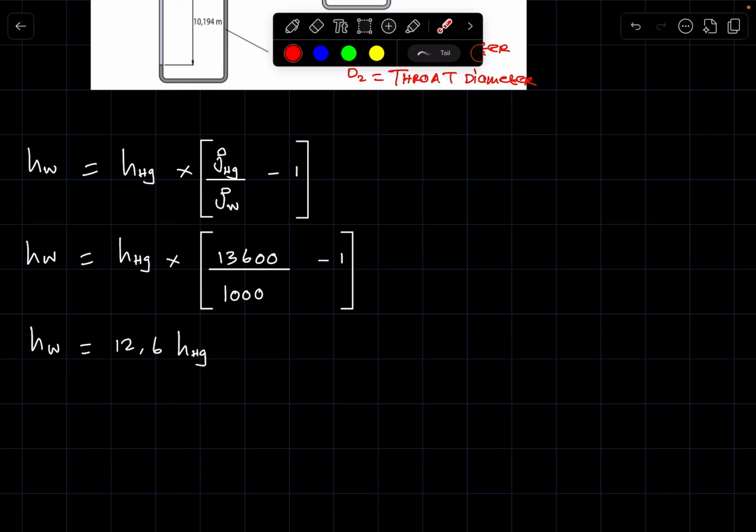that you're looking at, including air, including gases. If you're looking at a gas, then you should take note of that. You should be given the density of the gas, or enough data to be able to calculate the density of the air or gas. But you are also able to use this formula to calculate the pressure head difference. Using this formula, the only difference is that now the pressure head difference will be the pressure head difference of air, and this here will be the density of air.